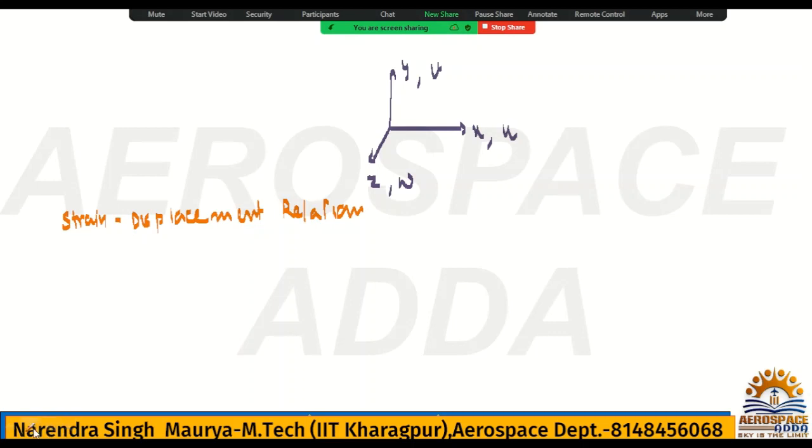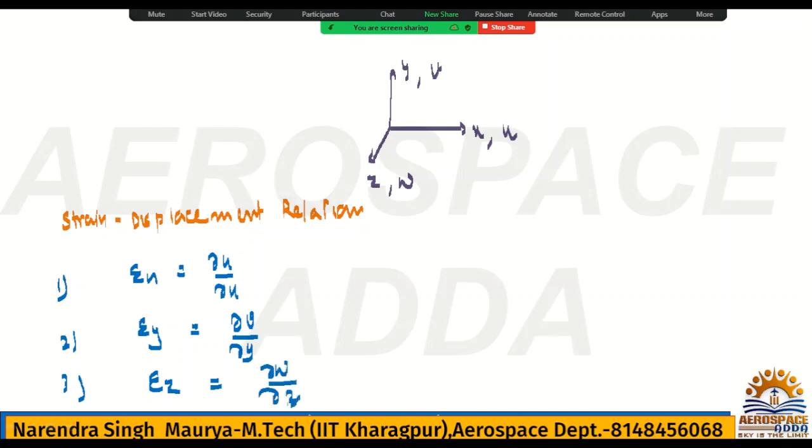Now you already have written this relation previously. First you write longitudinal strain, so epsilon x is nothing but dou u by dou x. Check, epsilon is the strain, u is the displacement, so it becomes a strain displacement relation. Second, epsilon y, dou v by dou y. Third, epsilon z, dou w divided by dou z. This is the strain displacement relation. Coming to fourth, xy plane, hence gamma xy, dou v by dou x plus dou u by dou y.